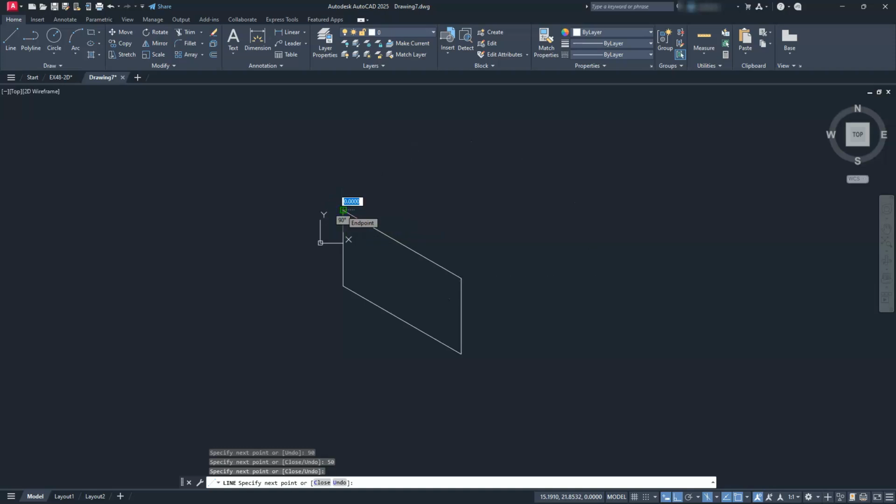Now I'm just going to hit F5. And that's going to switch me to isometric top. We could have done the exact same thing by coming here and clicking the fly up. But I'm just going to go this direction, a distance of 40. I'm going to come down this direction, a distance of, sorry, not 50, 90. And then I'll come back this direction.